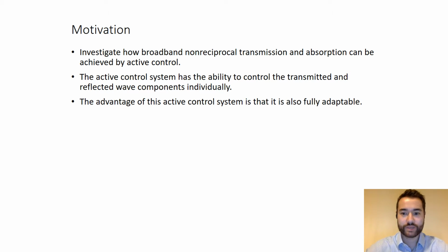Non-reciprocal acoustic devices based on resonant cavities typically only achieve non-reciprocal behavior over a narrow frequency range. This is because they're highly reliant on the resonant frequency of the passive resonators to achieve this behavior.